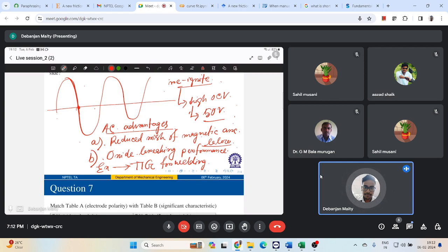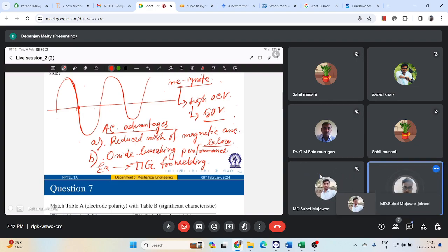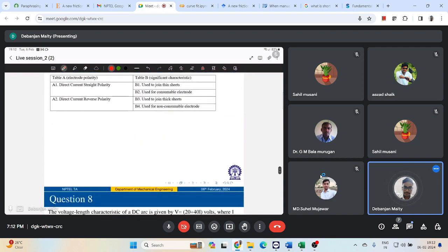Now for AC welding, the power source is always a transformer, and you can have some control for current adjustment, either by varying the inductance or by changing the magnetic coupling between the primary and secondary windings. So your transformer will have two kinds of windings, right?